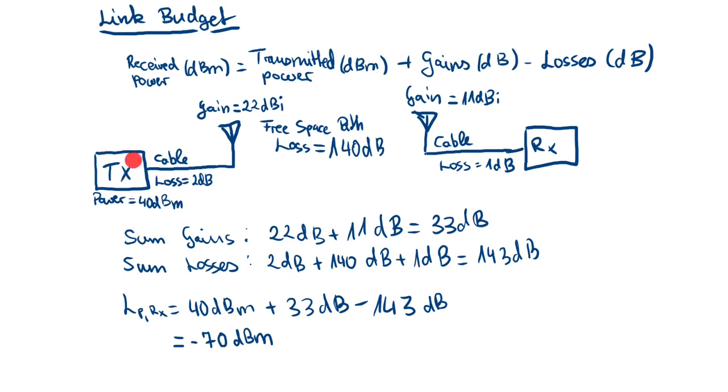And now we have a system. Here the transmitter contains all the things that we have already learned. It has digital signal processing with coding, spectrum modulation, filtering, and so on, and an RF front end with a mixer and amplifiers and filters too, and more amplifiers.